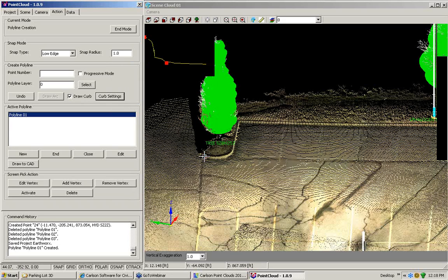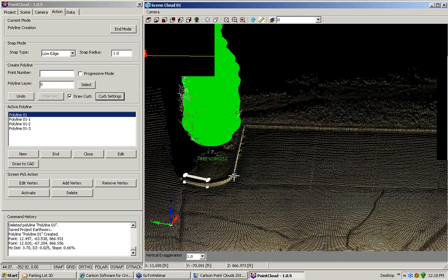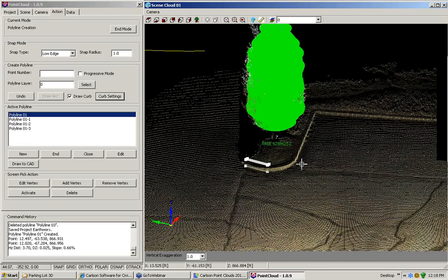So what I want to do is just pick a point, let's say right there looks like a good point, but I need to draw an arc. So I'll pick the draw arc command, pick on the center here, and I'll window in here so you guys can see this a little bit better. And then let's go ahead and pan this way. Then I'm going to tell it the end of the arc is right there. So it draws a classic arc for me.